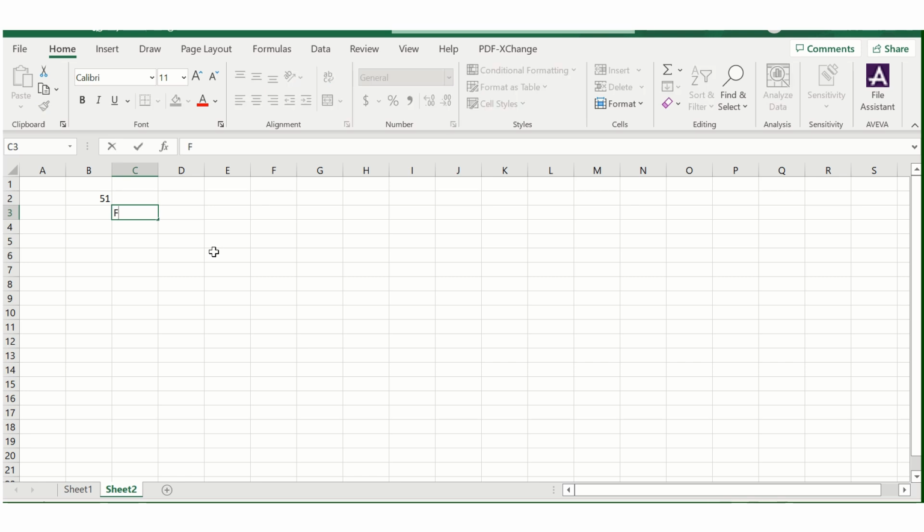So FLC is 218.7 amps, and CT ratio is, we have selected 300 by 1. Let's select 300 amps. So what will be the pickup?